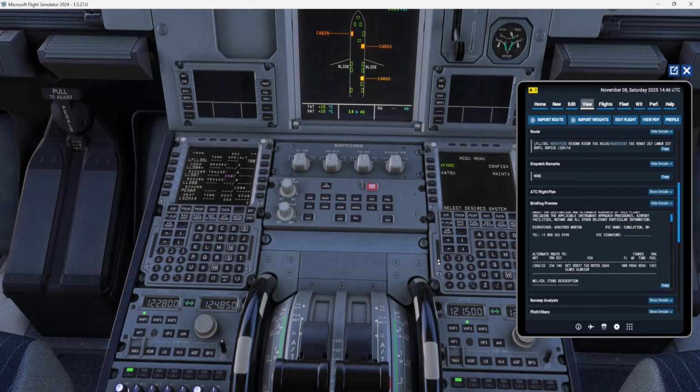And that's it. Then in case of engine out SID, I'm going to select over here. Let's select LFLL. Radial or radius is going to be 353, and then 20 nautical miles. I will upload it here, and we are going to have it. Then from here we go to LSZH, new destination, 14, and no star.